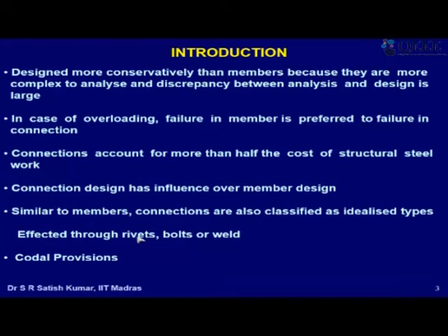And then welding is a very common way of connecting things, because for welds we don't need to put holes, and it is something we will do in the shop, that is away from the site. Basically what we mean by shop is under controlled conditions. It's possible that at the site you set up a fabrication shop and do the welding inside that controlled condition, that is under a covered roof, or sometimes we may have to lift the beam, hold it with a crane at the place where I want to do the welding, sit on the beam or somewhere, and then do the welding.